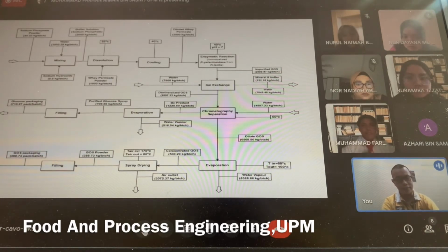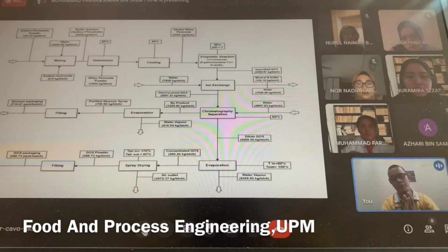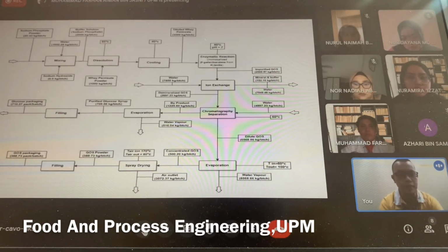So you justified. You as a process engineer, you have to justify every instrument that you use. Understood? So, for example, we have a lot of heat exchangers in the market. We have tubular heat exchanger, we have scraped surface exchanger, we have plate exchanger. So, why do we use a plate exchanger? Because of good energy transfer, because there is a big surface area. But you have to remember when you use the plate exchanger, the flow rate will be lower than a tubular heat exchanger, right? Yeah, you have to understand.